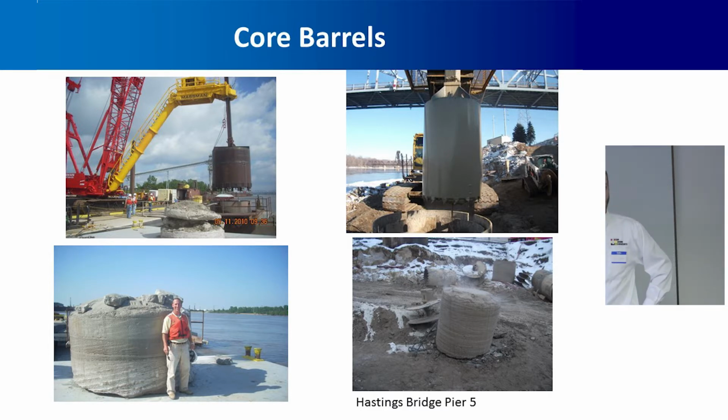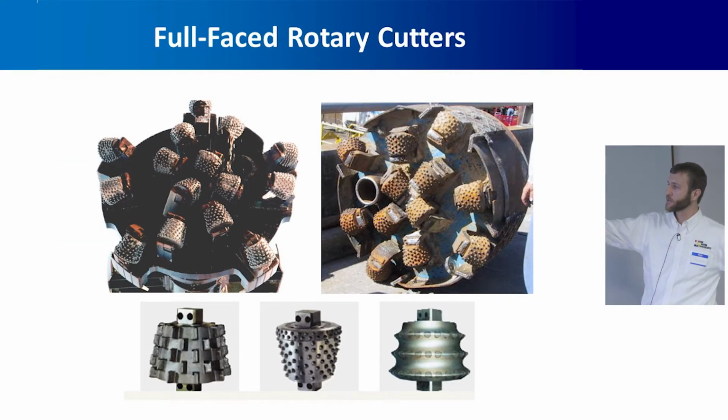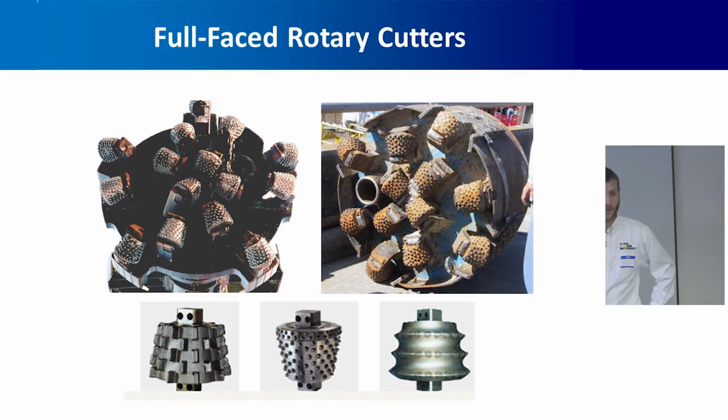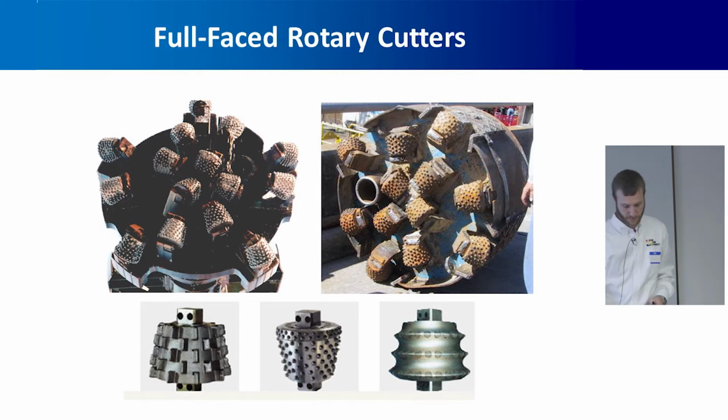This is looking at the cutting face of the reverse circulation rig. You can see it's got cutting wheels that bust up the rock. You can use different types of wheels for different types of rock. And this hole right here is what circulates the fluid. That hole is essentially airlifting or vacuuming the cutting surface as this thing goes around.